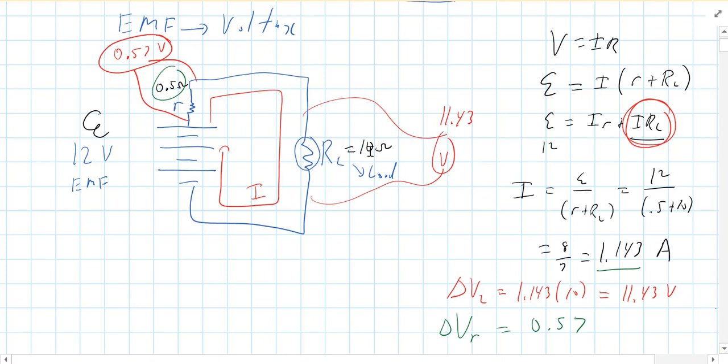Their resistance is rather low, and they draw a lot of current. So, a lot of current comes out of your wall socket. Well, if a lot of current's flowing, that means you're losing some voltage due to the internal resistance of the wires and such. Therefore, anything else that happens to be plugged in at that moment will lose voltage as well, so the lights will dim.